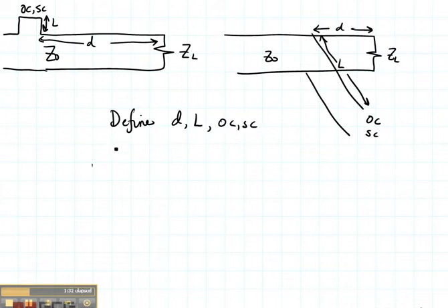One note that I'm going to make is that in this class, Z0 is going to be constant throughout our transmission line. In microwave engineering, you'll learn how to design stubs that might have a different characteristic impedance from the line.